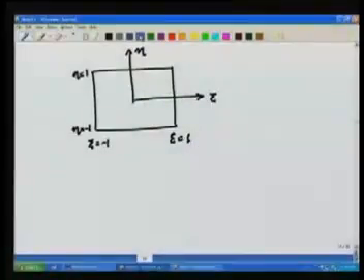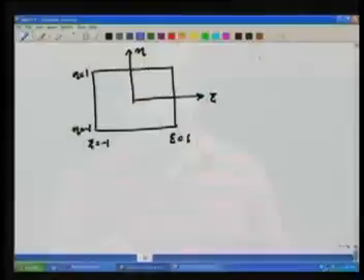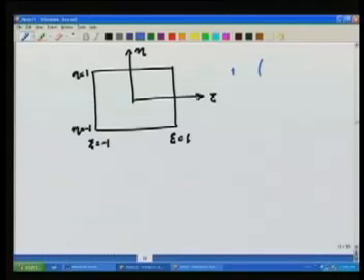and that is going to give me the integration rule for the 2D. The 1D rule is already known. So let's say, how are we going to make it? If I have a linear in psi and a linear in eta as my integrand, so it's a bilinear integrand, then the rule is governed by n greater than or equal to (p plus 1) by 2, okay, where p is the order in each direction.